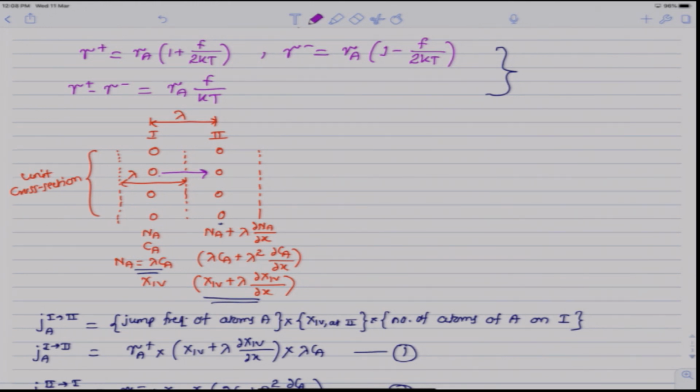And we know the increase in Gibbs free energy when an atom is added to a homogeneous alloy is the chemical potential of the atom. We can similarly define the chemical potential of a vacancy. It is the change in Gibbs free energy when an atom is removed from the interior and placed onto the surface, in which process one extra lattice site has been created.